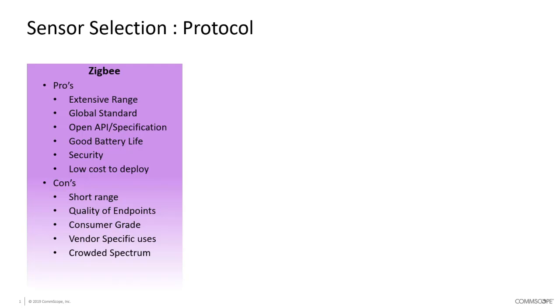One of the big things really with Zigbee is the concept of clusters that Zigbee uses. Now, this is good because it clearly defines the capabilities of the device, but there is also a lot of scope in those clusters for vendor-specific applications. So it's very easy for somebody to build a standard compliant Zigbee device that uses standard Zigbee clusters and then throw in a couple of proprietary clusters in there, which means that most applications are unable to talk to it.